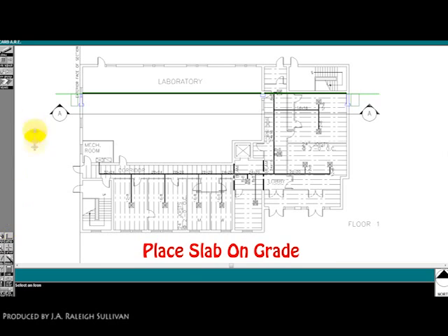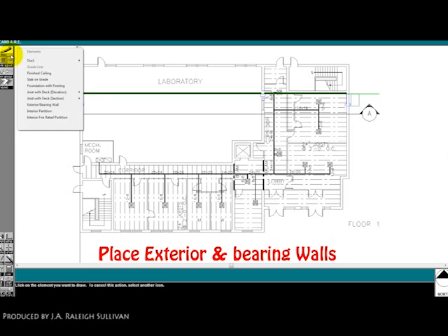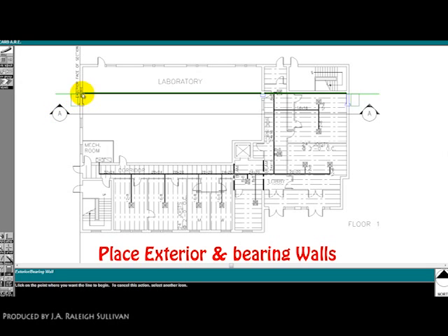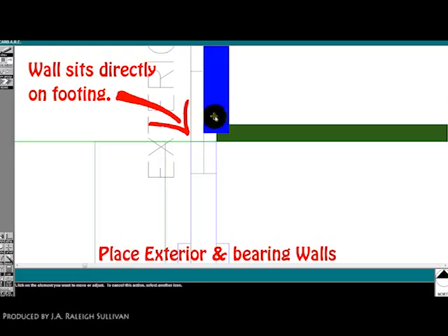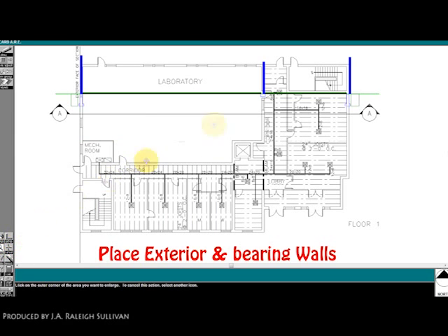We'll go ahead and put the bearing walls in now. Just like with the other elements, we'll quickly plop in the bearing walls, and then we'll fine-tune, adjust them when we zoom in. So it sits right on top of the footing. Now we'll work on the interior footing.